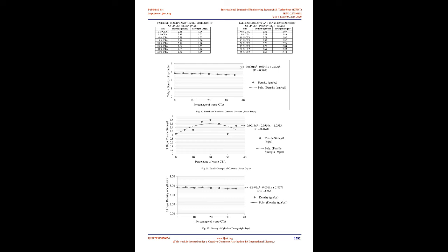Elongated aggregate weight, gm. Flakiness index of natural crushed aggregate from Kotra crusher was obtained as 26.93% and elongation index was 38.25%. Flakiness index of CTA was obtained as 5.79% and elongation index was 34.15%. This was better than natural crushed aggregate. So manually crushed tile aggregate has better flakiness and elongation behavior than natural aggregate.